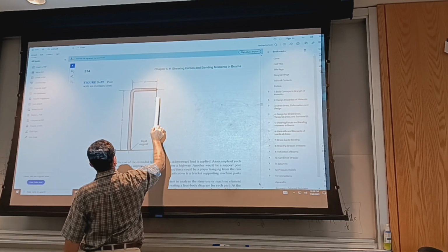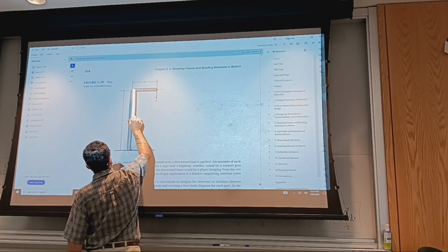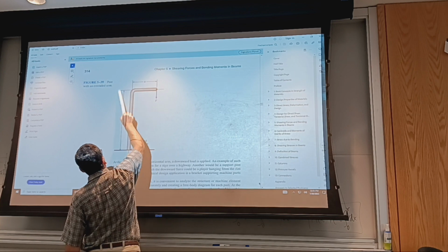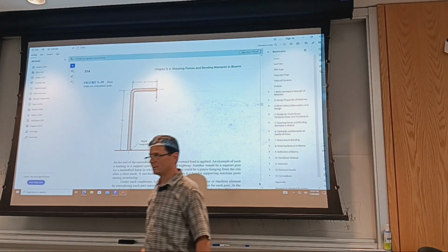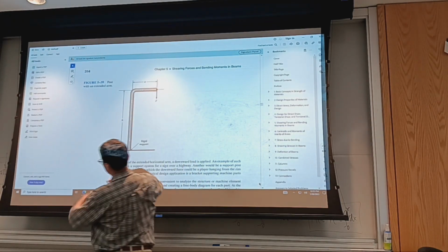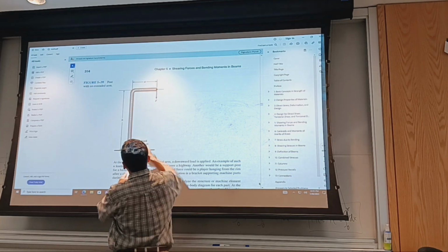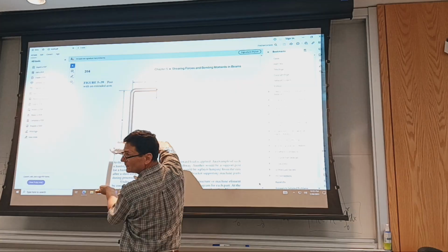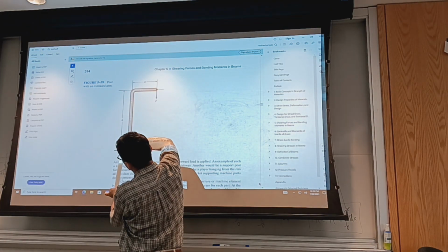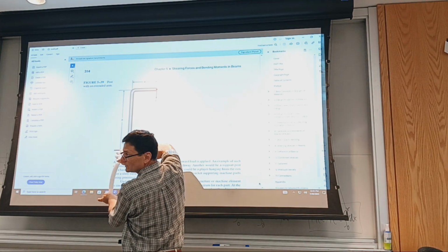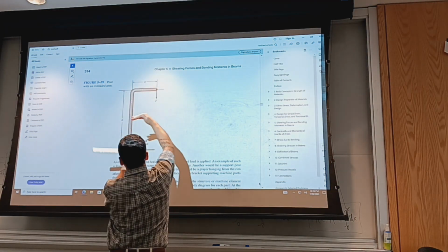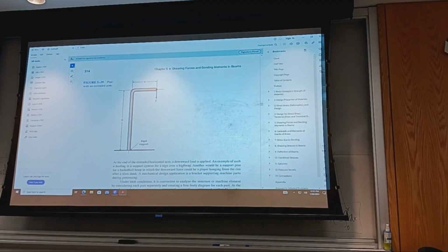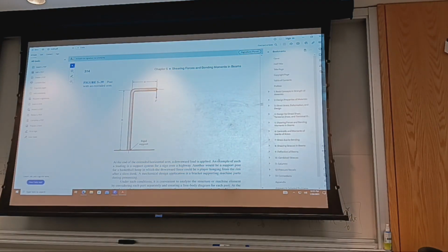And so you move the force at the bend; it will be like a compressive force, but then you have a moment that goes counterclockwise. So the horizontal beam is like a cantilever, and then the vertical beam is a cantilever that has a moment applied to its end, plus a compressive force. Does it make sense? So again, you take pieces, separated conveniently. You need to analyze the system as a whole, and then you can analyze them individually.